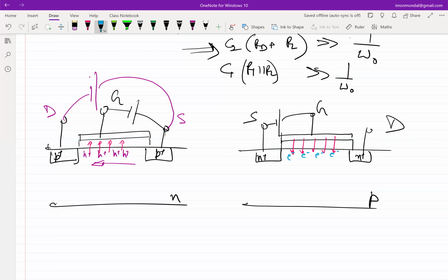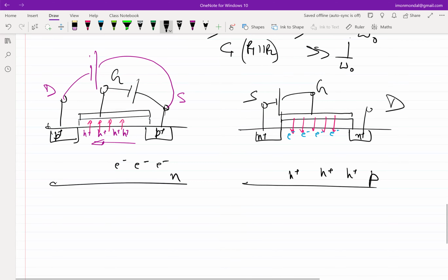Note that here the mobile electrons are carriers of inverted polarity with respect to the bulk. In the PMOSFET case, the bulk was electrons, and the holes gave you the channel, which can be controlled by the gate. In the NMOSFET device, the bulk is filled with holes, and you are developing a small channel of electrons by controlling the gate voltage, or gate-to-source voltage. So in this case, the gate voltage has to be higher than the source voltage, just because you want the electric field in the direction I have shown. Everything else is the same.